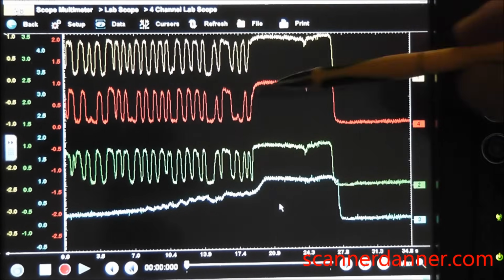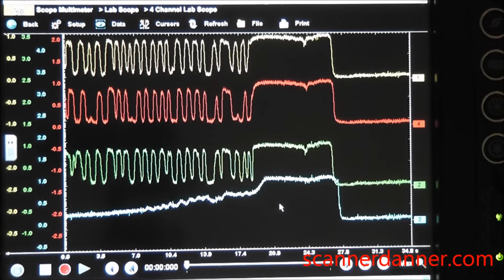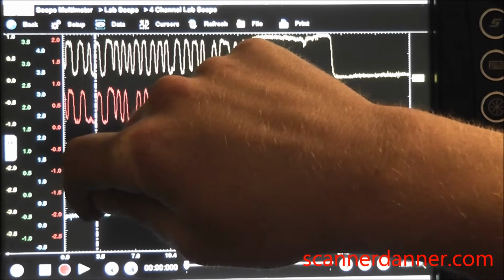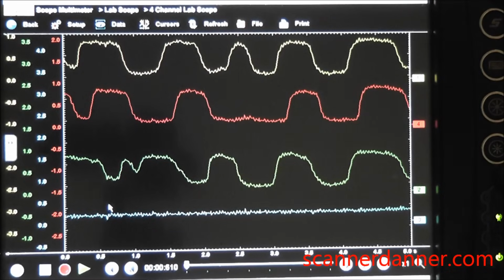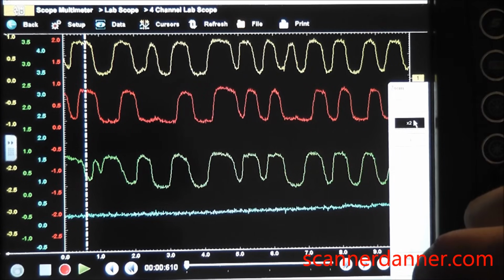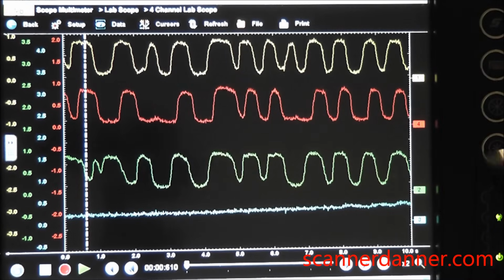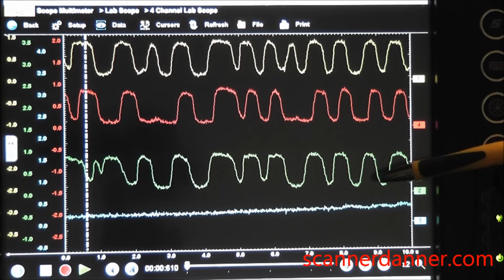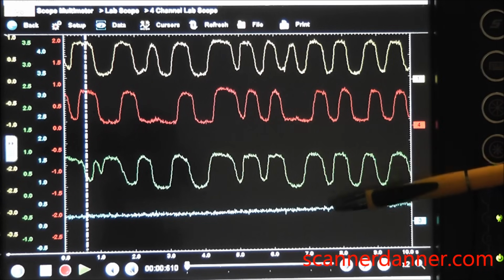So if you would just look at this area in here, I want to talk about this for a second, because I see a lot of material out there that is kind of true, but I just don't like blanket statements. So what we'll see in material out there is they'll talk about these two and say, okay, we have a bad cat on bank 1, and I would agree. And that they'll look at these two and say, we have a good cat on bank 2. This one is the one that we have to worry about.